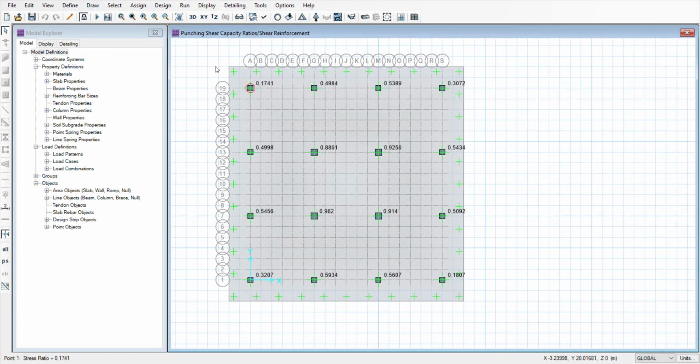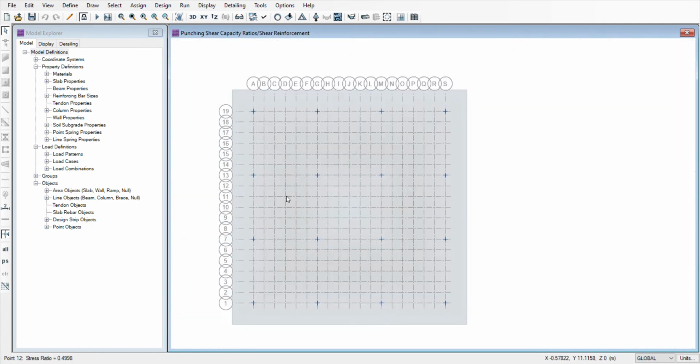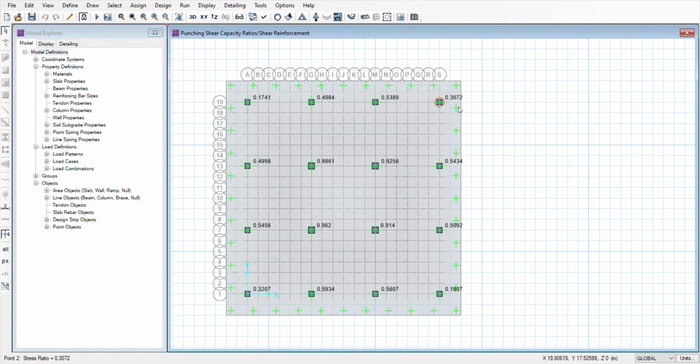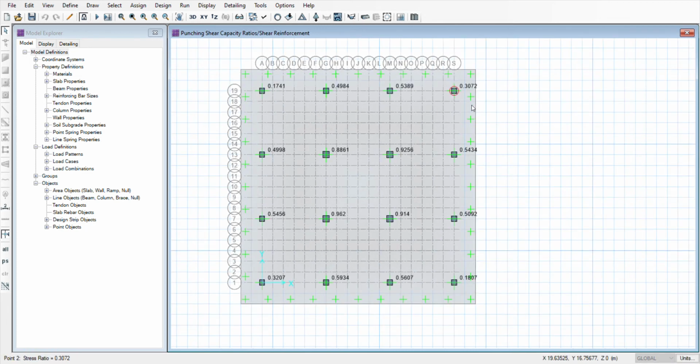I have selected the grid sheet and I have drawn a slab with extensions of 2 meters on all sides of the building plan, as you can see here. This is because if we do not consider the extension, we will end up with the corners of the columns. So to provide relief, I have considered an extension of 2 meters. Then the actual length and breadth of my mat foundation results as 22 meters.